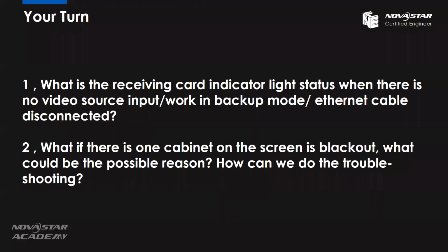Okay. First we will check our network cable. And if our network cable is working perfectly, then we will check our receiving card. Okay, the network cable, receiving card, anything else? Power supply. Maybe sometimes the power supply is the issue. Yeah, could be. Anything else? No. That's all? I don't think so. That's all. Okay, thank you. I would like to know the answer. Thank you.